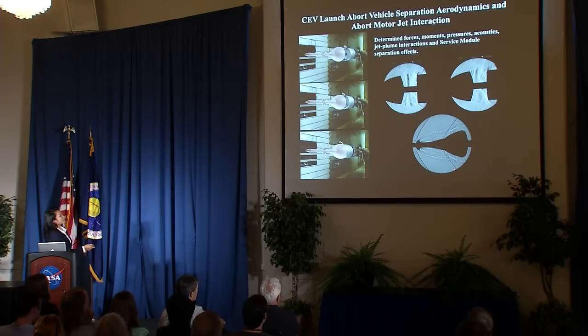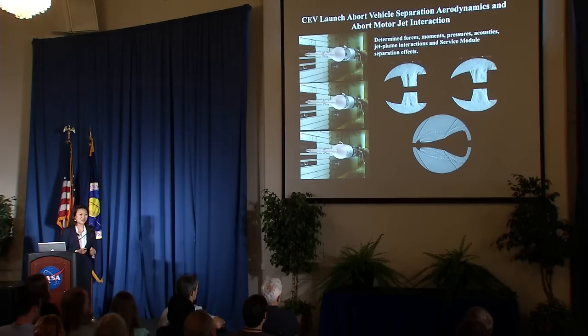On the right, you have a bunch of Schlieren photos. You can see the density gradients are right over here. They're usually shocks, and a nice shock in the front of the model over here, and a second shock right here. So why is this important? Well, where do the astronauts sit? They sit right here. So we need to understand very well what is happening during this process.